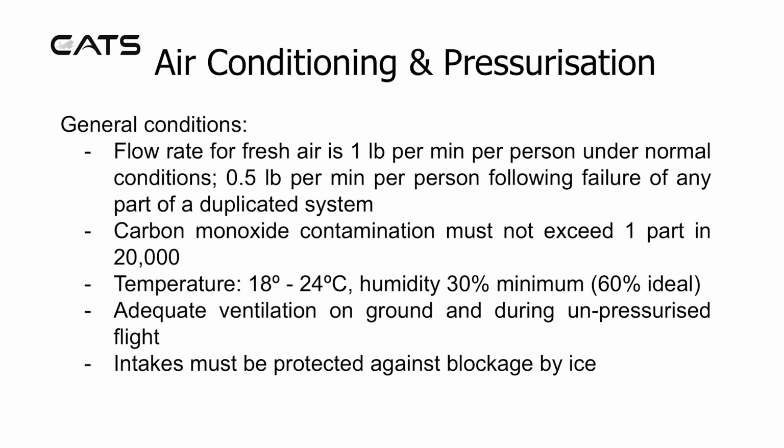Air conditioning and pressurisation. The general conditions. The flow rate for fresh air is 1 pound per minute per person under normal conditions, or 0.5 pounds per minute per person following failure of any part of a duplicated system.